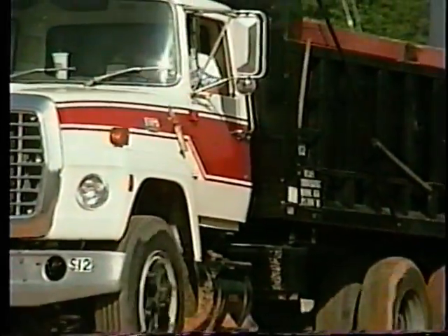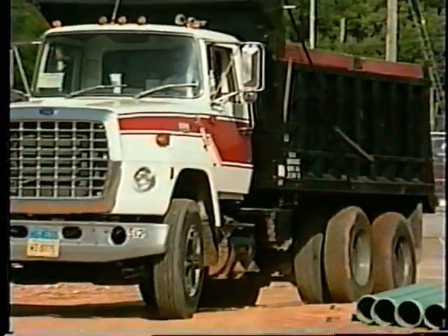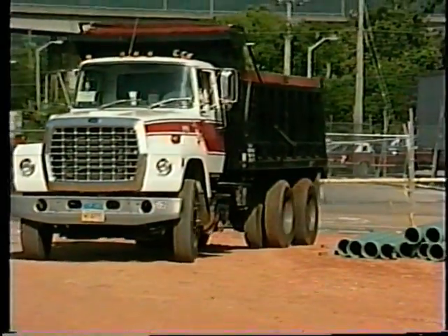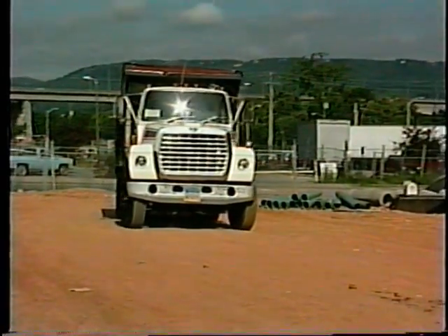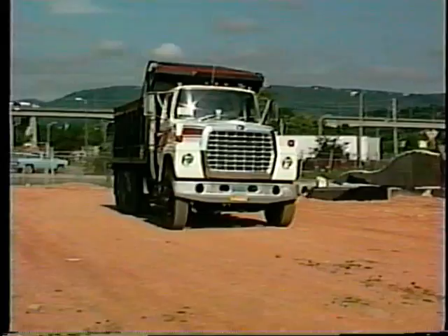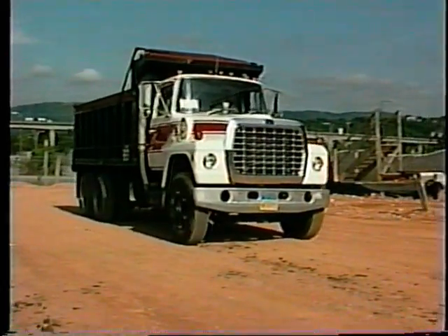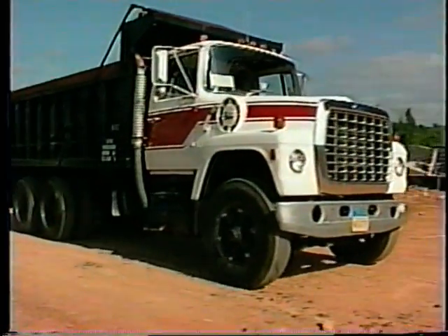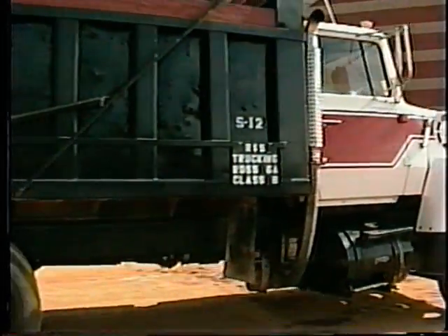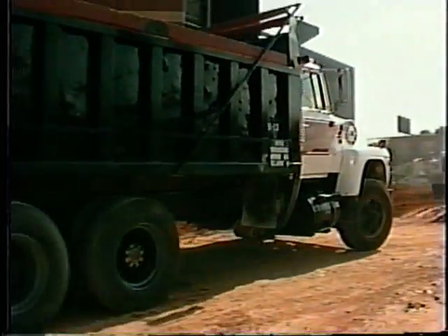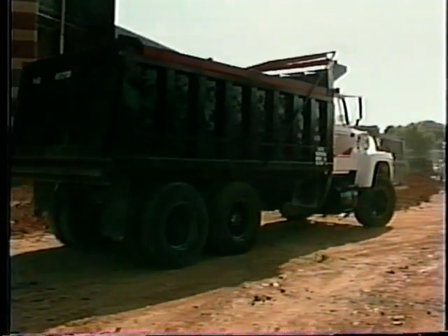Because thermoplastic sewer pipe lacks the rigidity and strength necessary to support expected earth loads and live loads, special installation requirements apply. An underground pipe is expected to support the earth load, expected live loads, and traffic loads, while limiting pipe deflections so obstructions to flow and joint leaks do not occur.